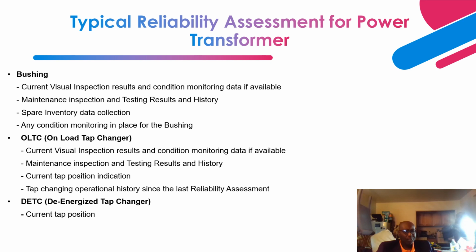Manufacturers of bushings provide instructions on how the bushing should be stored. The goal is to have the oil all over the capacitive layers. It should be stored in such a way that none of the capacitive layers are deprived of oil, because that can create voids and pockets, and can result in partial discharge activity and failures when it is brought into service.